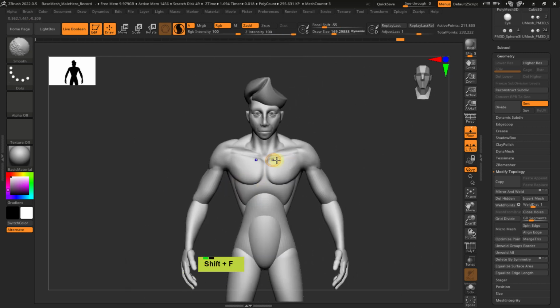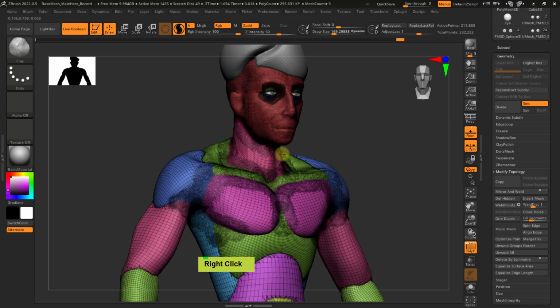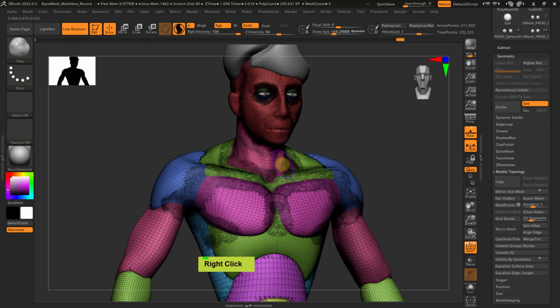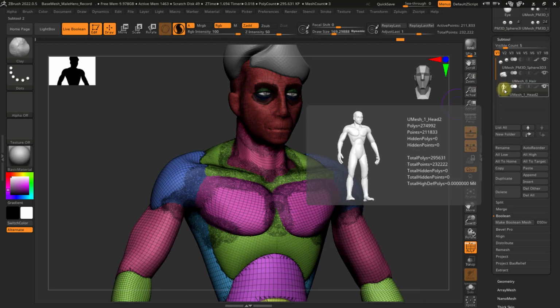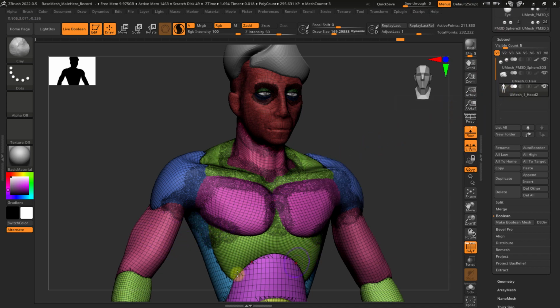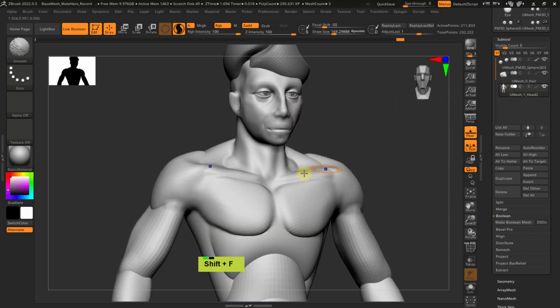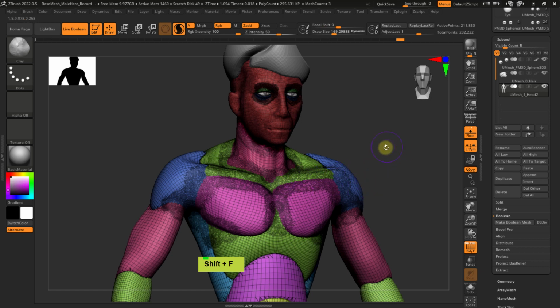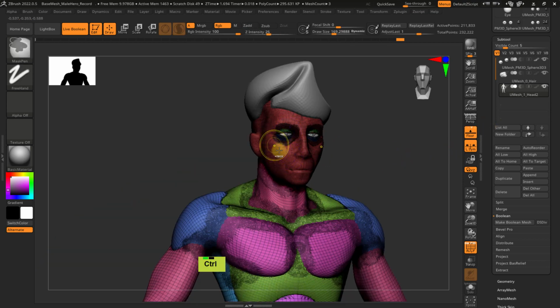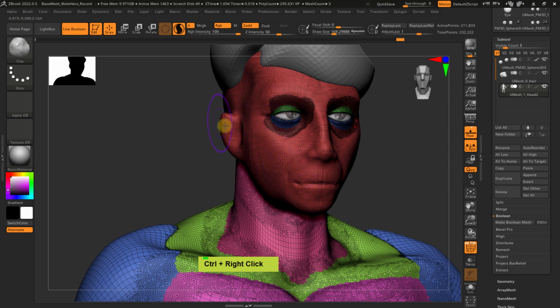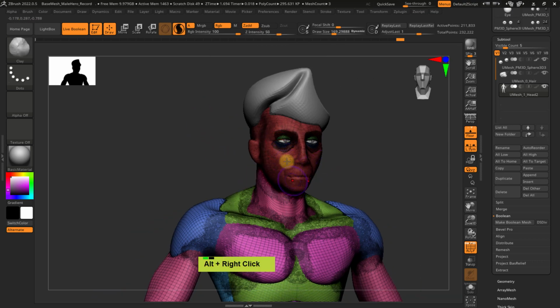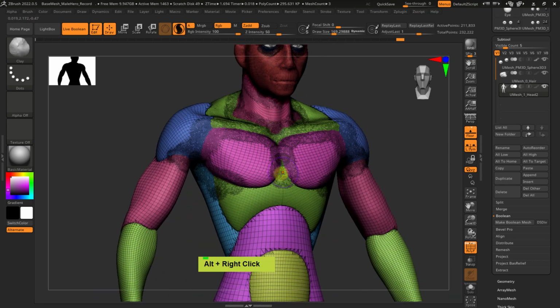Now what we want to do is, this is a quite Frankensteined mesh. So we have no subtools, but everything is welded and in different resolution, and some parts are detailed, some are not as much. So first of all, we want to have a good overall mesh. For that, Dynamesh will not do. Dynamesh is great for creating single parts, or working on a silhouette, creating the ears, nose, pulling out things. That's working great.